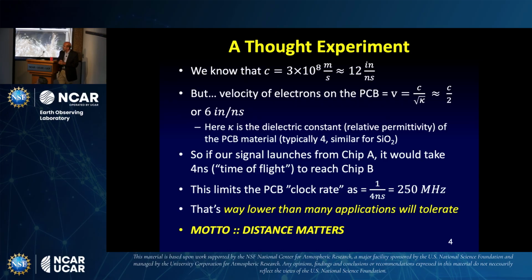So our clock period would be no shorter than 4 nanoseconds, which means the clock rate would be just 250 megahertz.